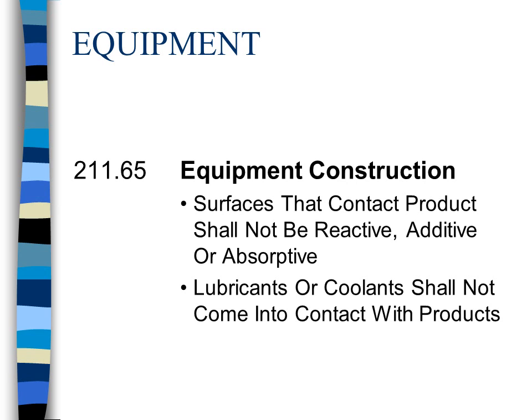The equipment construction: surfaces that contact the product shall not be reactive, additive, or absorptive. When we are filling liquid oxygen reservoirs or liquid nitrogen dewars, we want to make sure that where we are filling them is clean and free of any grease, oil, or other contaminants. Lubricants or coolants shall not come in contact with medical gas products. To give you an example, oxygen, for example.